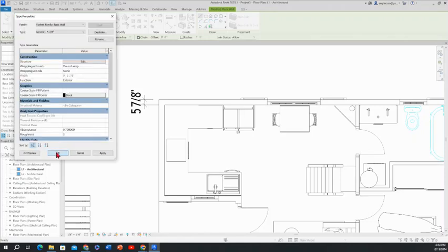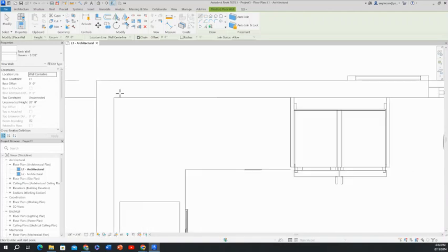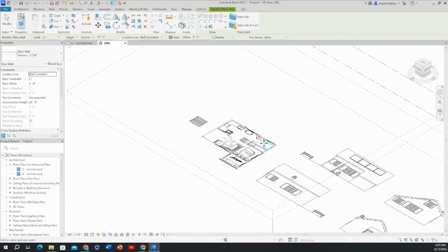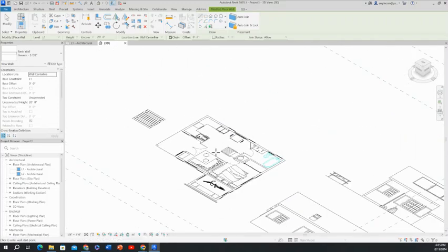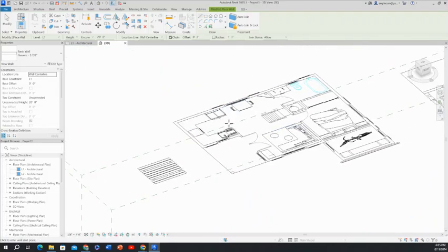Okay. And now I can start drawing my walls. You're gonna notice that there are witness lines showing us the center lines. But let's do this one a little bit more graphic. So let me go to the 3D view, the basic 3D view, so I can go over this 3D view here. Let me navigate a little bit using Shift and the wheel of the mouse.